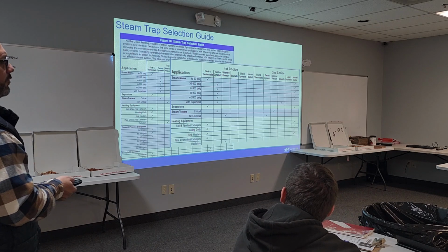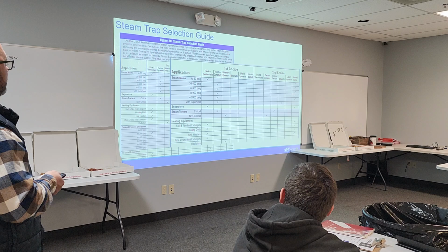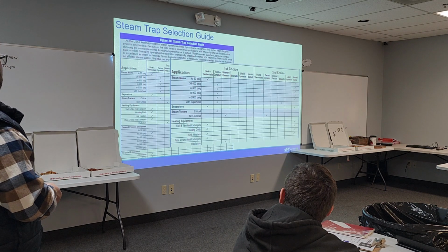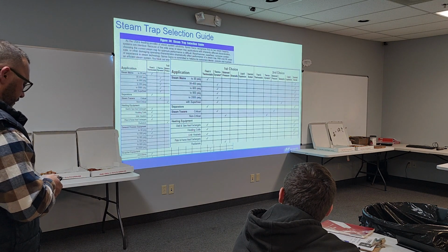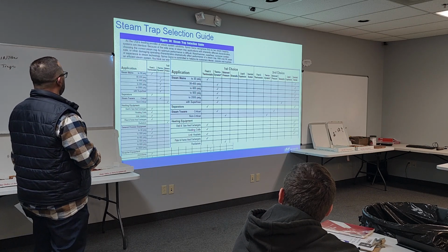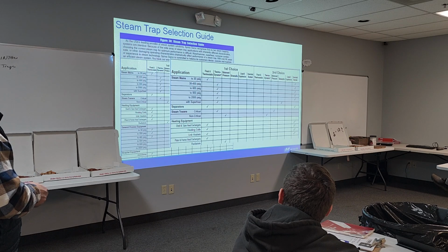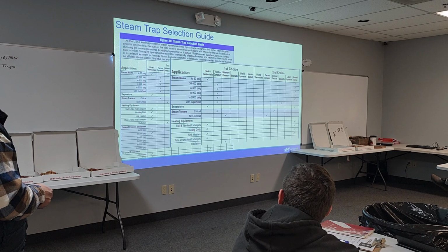Again, we talk about, are you a Ford guy, are you a Chevy guy? It's really not one always right answer. This is kind of right out of a Spirax Sarco steam trap selection guide. This is steam mains. They're saying our first choice, floating thermostatic. They're saying really that's it.